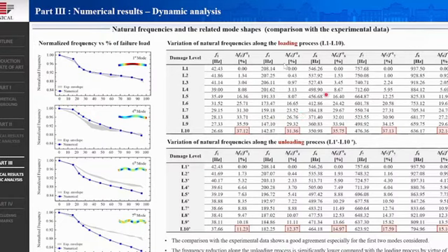The frequency reductions are evaluated for both the loading and the unloading processes, and we obtained a frequency reduction of about 35% for the first one and of about 15% for the second one, highlighting that the frequency reduction during the unloading process is significantly lower than the loading one by virtue of the stiffening effect given by the partial crack closure phenomena, which is effectively simulated by the proposed model.